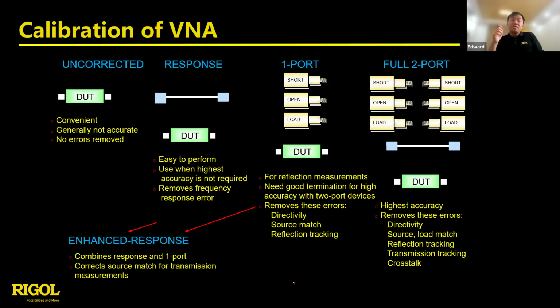For example, previously I used to work in the lab to calibrate 100 gigahertz network analyzers. We used probe stations to probe the semiconductor wafers. So we used the calibration plate and spent over 20 hours. But if you get a successful and precise calibration result, the test procedure takes only 1 minute.